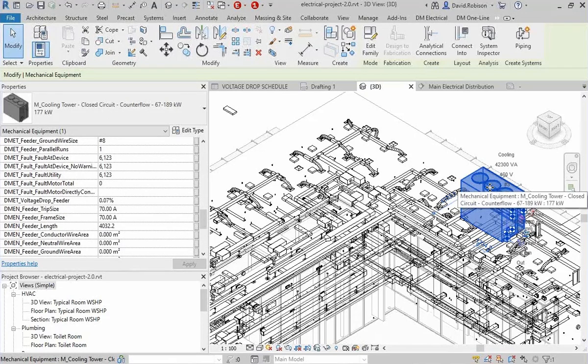So anywhere you're scheduling circuits, so in your panel schedule, you could put the fault on the circuit as well if you wanted to do it there. So that was requested by people just because you've got a lot of equipment and you need to have the fault at them. Previously, you had to put in kind of a fake piece of equipment. It worked, but this just gets it to you a little bit more directly.